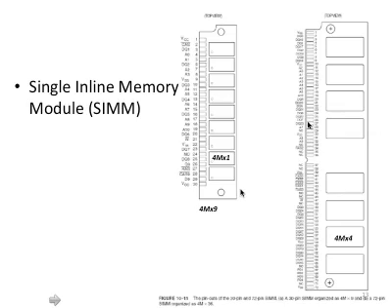How many address lines for this chip? That is to figure out 2 to the power x equals 4 million. So that's 22. Conceptually, you need 22 address bits to access these 4 million locations. But because of the row access and column access, you essentially have 11 bits for the address to this chip.